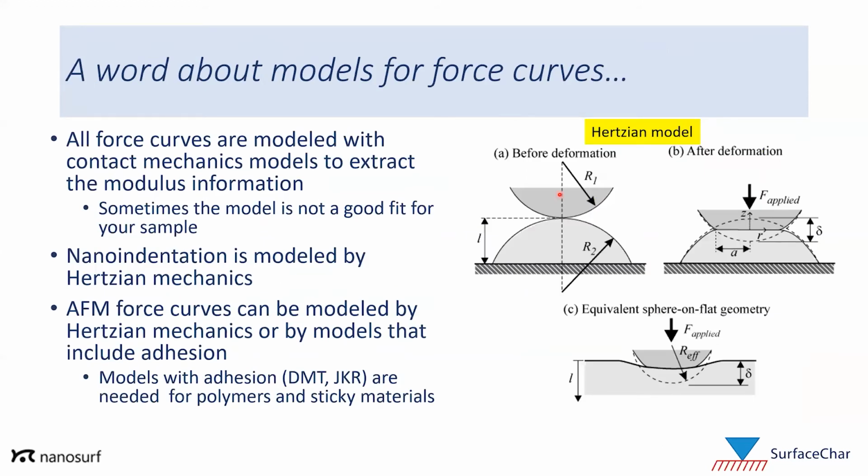Okay. So a word about the models we use for force curves. No matter what instrument you use, whether it's the AFM or nanoindenter, all the force curves that you collect are modeled with contact mechanics models in order to extract that modulus or stiffness information. And I will be honest, there are times that the model simply is not a good fit for the sample.